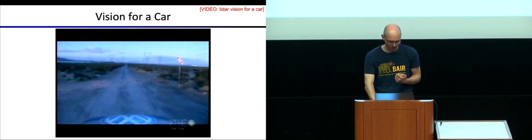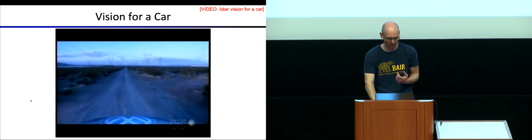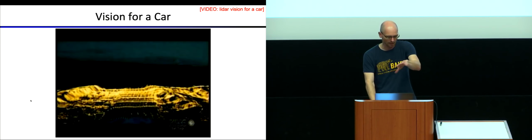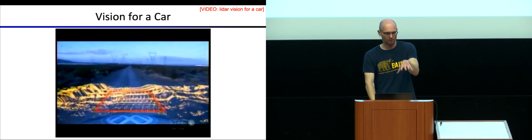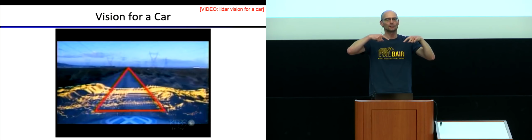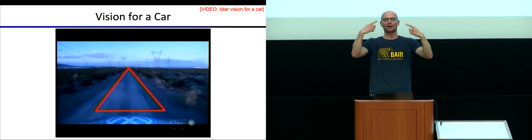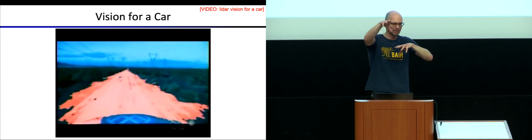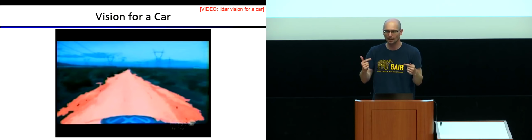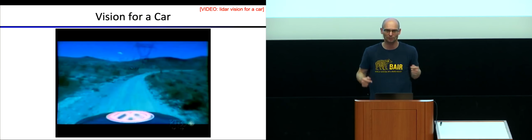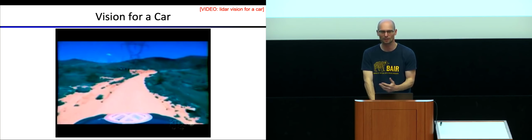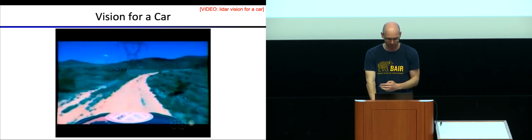Well, the way you could build vision for a car, because labeling is expensive, you could decide that you drive your car, and wherever you ended up, the LiDAR can tell you what is road, not road, because it's nearby. After the fact, you can backtrace what it looked like 2 seconds before that, 5 seconds before that, in your video stream, and then automatically label it as road or not road, and that way your camera system can be trained to look further ahead. It's called self-supervision. And self-supervision is a trick that's very widely used to reduce labeling efforts.